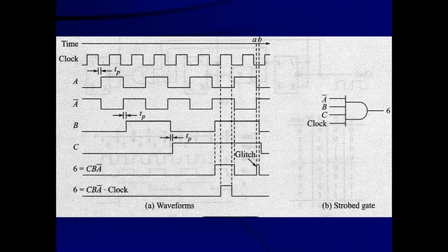Now waveform B is drawn here. You can see that waveform B is complemented when the output of A triggers flip-flop B. But waveform B does not occur at the same moment; it is also delayed by the propagation delay time Tp.